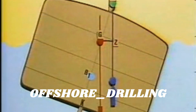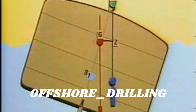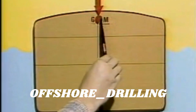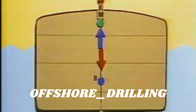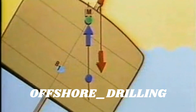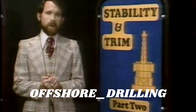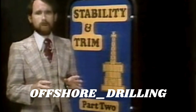And finally, we said that where M is above G, we have stable equilibrium or positive stability. When M is at G, we have neutral equilibrium. We also said that where G is above M, we have negative stability and an upsetting tendency. If you did not do well in the first examination in the study guide, replay and study Part 1 again. A lot of the material from Part 1 will be needed to understand what we'll cover in Part 2.